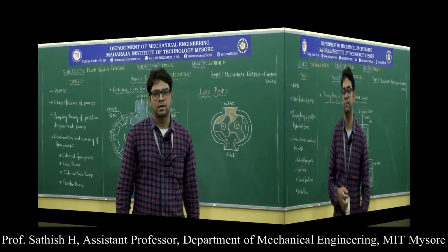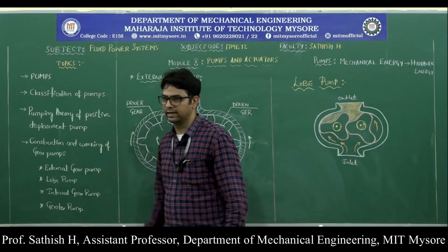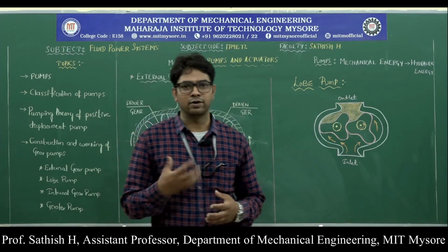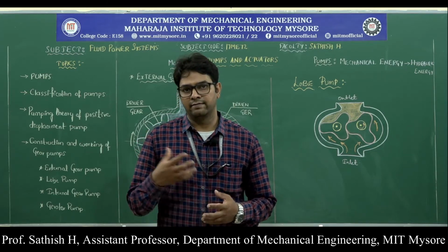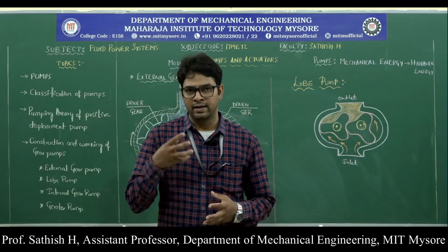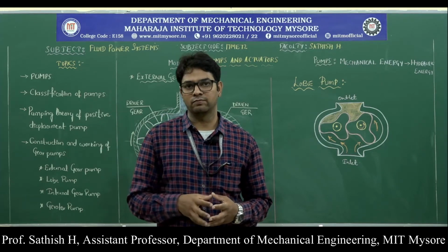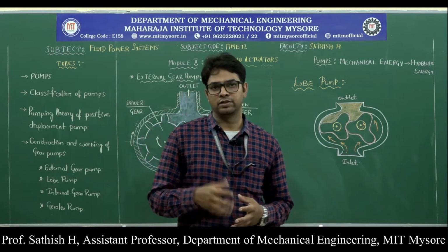Now let us go to the next topic, construction and working of the gear pumps. As I said before, gear pumps are positive displacement pumps. For every revolution of the shaft, a fixed volume of fluid is discharged into the hydraulic system at the outlet. Those are called positive displacement pumps.